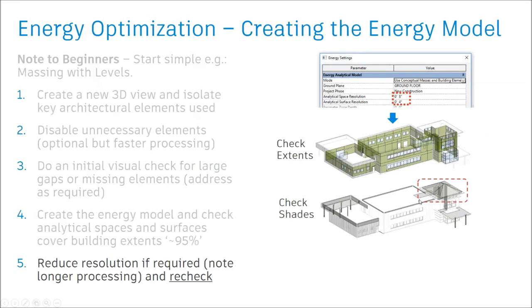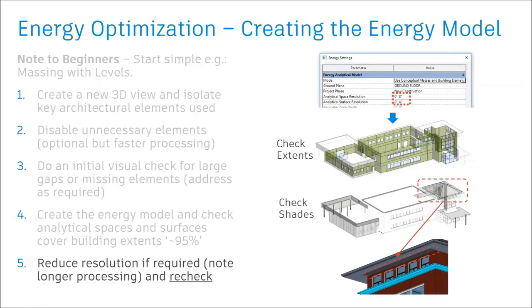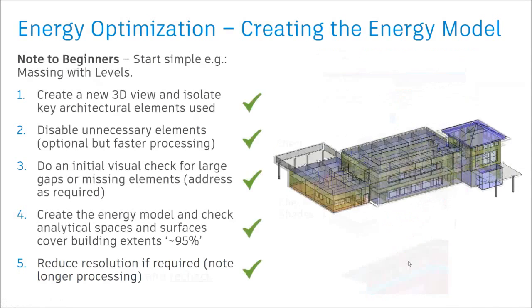But this roof area here seems to be appearing as a shade when it shouldn't. And if we then take a closer look at the physical model, if you actually look underneath here, you'll see that there's a big gap in the roof. And all you need to do is fix that, and the model will then resolve itself.